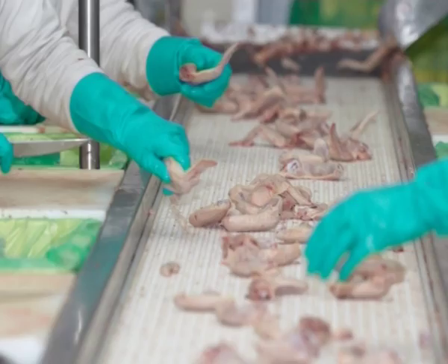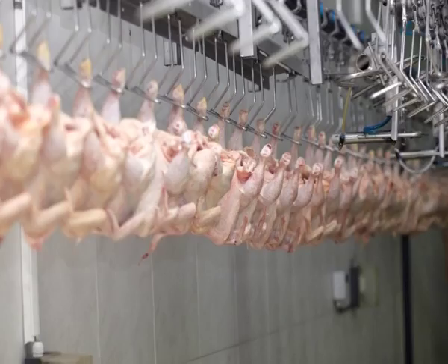For example, in the meat and poultry industry, the major characteristics of the wastewater generated from slaughterhouses and poultry processing are a high organic load, which may go up to 8000 milligram per liter BOD. It also has a high concentration of oils and grease, salt, nitrogen and phosphorus, with suspended solids at 800 milligram per liter or more.